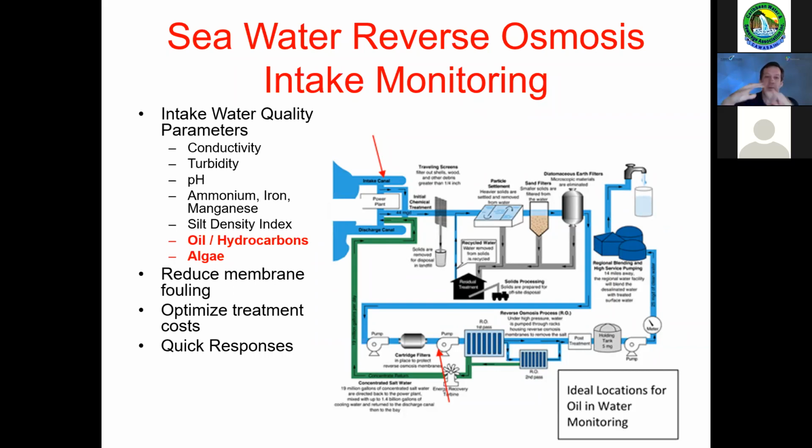The structure of the molecules is such that water can pass through the lattice, whereas salt and other things cannot. Then below that, there's a polysulfone layer, which is a structure that the polyamide layer can stick to. The polysulfone is very thin. And then there's a third layer that's really just a backbone or a skeleton for everything to sit on and produce a membrane that you can actually hold and put into a spiral.